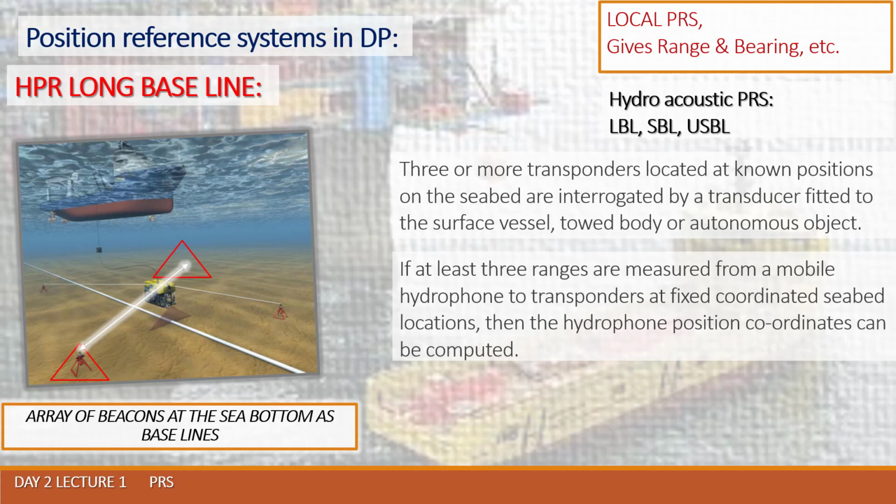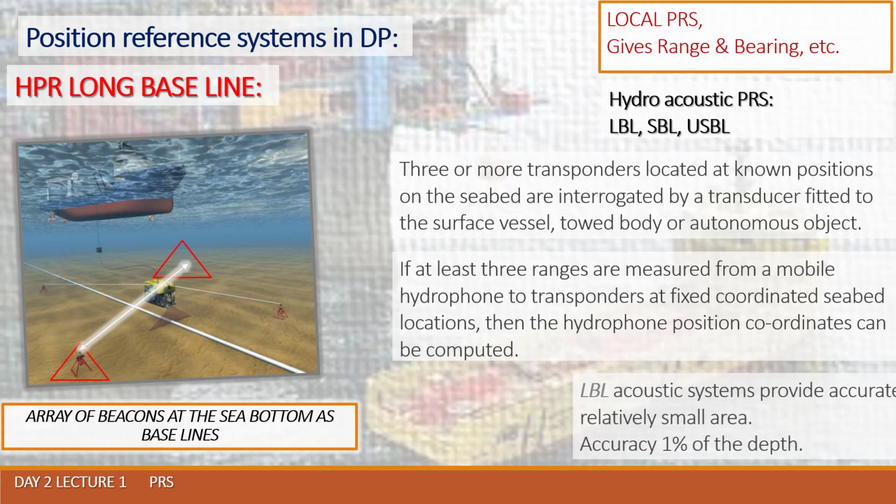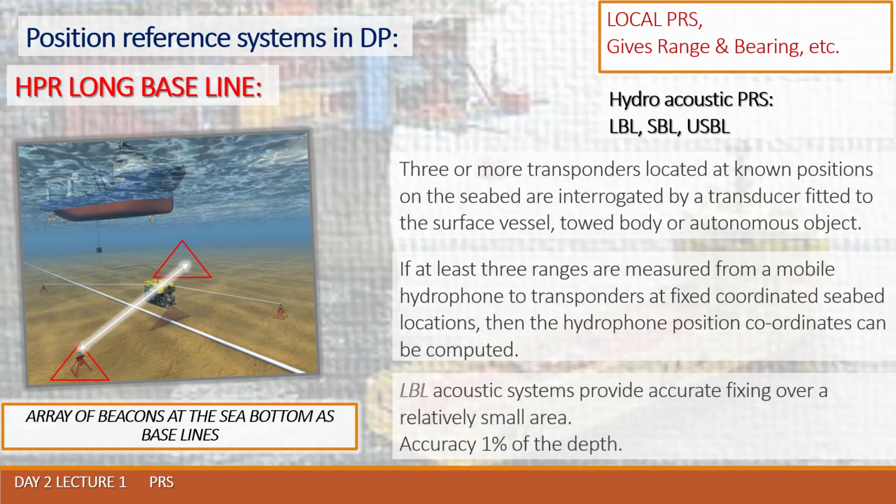Long baseline acoustic systems provide accurate fixing over a relatively small area, and the accuracy for that system is about 1% of the operational depth. This system is normally used for long-term projects and is not popular for some temporary job.